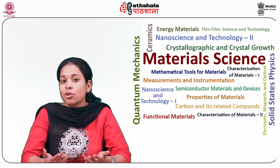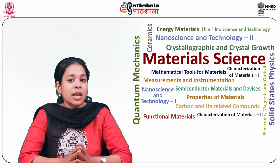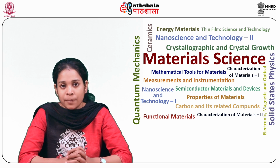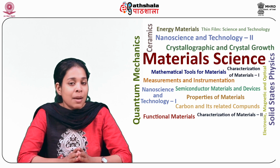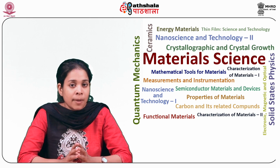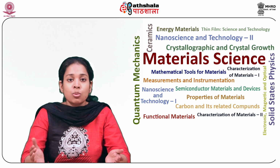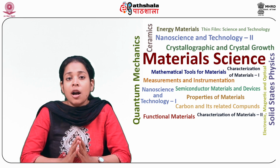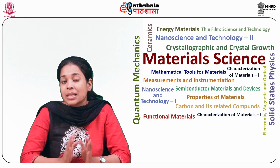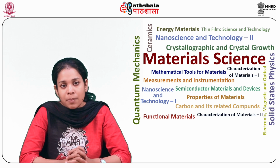Due to the presence of two different media having different permittivities, the wave propagates with different speeds in both directions. So this results in quasi-TEM mode. Quasi-TEM mode is also known as hybrid mode, which has non-zero electric and magnetic fields in the direction of propagation. The hybrid modes are higher modes which occur with cutoff frequencies different from the direct current, that is 0 Hz, and are undesirable.